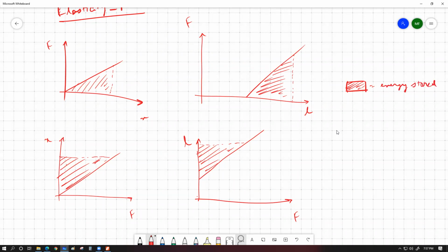So if we have a graph of force versus length of the object, then the graph would not start from the origin, because this intercept part over here basically represents the object's original length or unstretched length. So before deformation, this is the length that the object starts with. So when no deforming force is applied, then the object still has some initial length to start with. That is this length. And then as the length of the object starts to increase, or the object starts to undergo deformation,